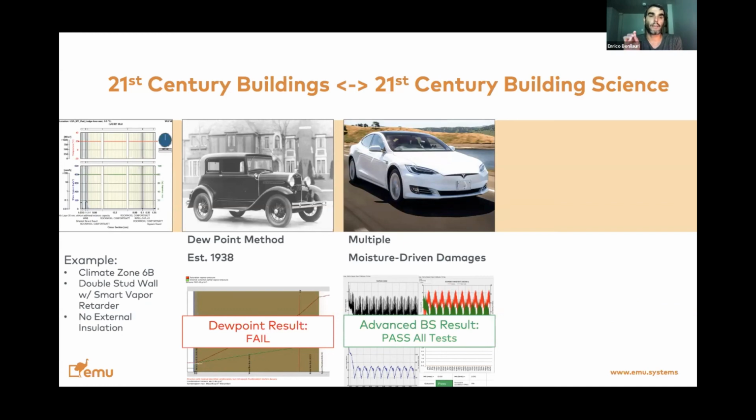You can have biological decay, for example, what we saw in the roof in the previous slide, and that can happen even if your roof is entirely dry. But if the moisture content of the wood exceeds 20%, that has very little to do with actual condensation. And then you can have other phenomena, including interstitial mold or corrosion, that also can take place without any liquid condensation occurring inside your assembly.